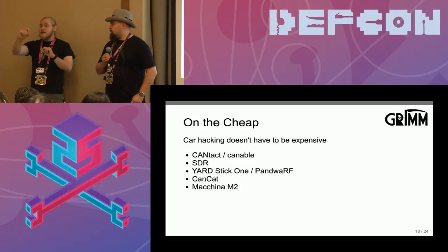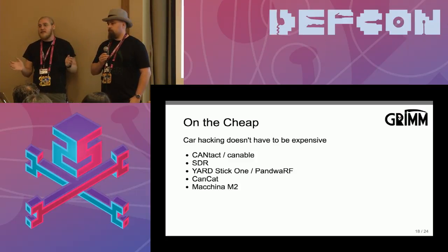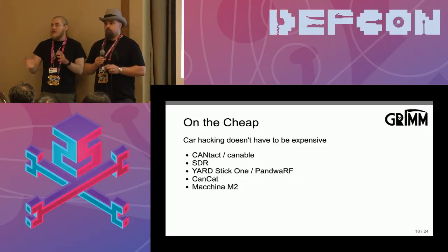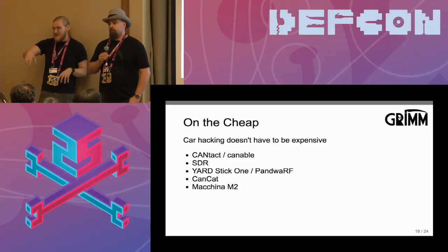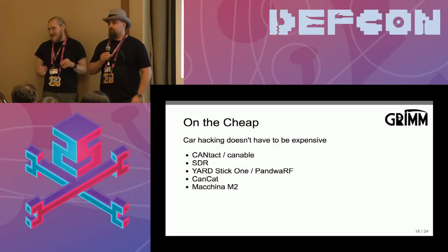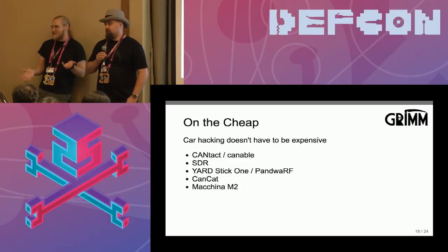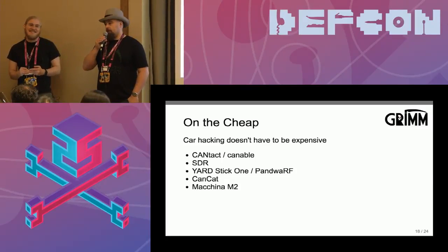It's literally just a microcontroller that has a crystal on the side and a CAN transceiver. It's super basic. The one thing you don't get in this sort of hardware is any sort of galvanic isolation. So some of the more expensive CAN adapters will actually protect your PC from high voltages that the CAN bus might experience if something goes wrong. These are just directly connected. I've never had a situation where that's important, but it's something to be aware of. Yeah. Still, a Cantact and a USB hub is a lot cheaper than anything you buy from Vector. Yes.